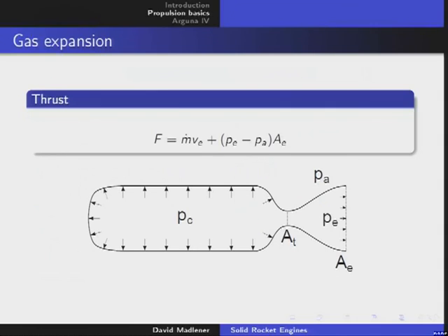So, back to thrust. We have, during the reaction, a certain chamber pressure, and this pressure is exerted on the surroundings of the chamber, and hopefully the chamber doesn't crack. So the gas cannot flow out. The only way to flow out is through the nozzle. And of course, that's what we want. And at this point, the pressure is not zero, but has some exit pressure, we call it. And as we start here on Earth, we have some ambient pressure.